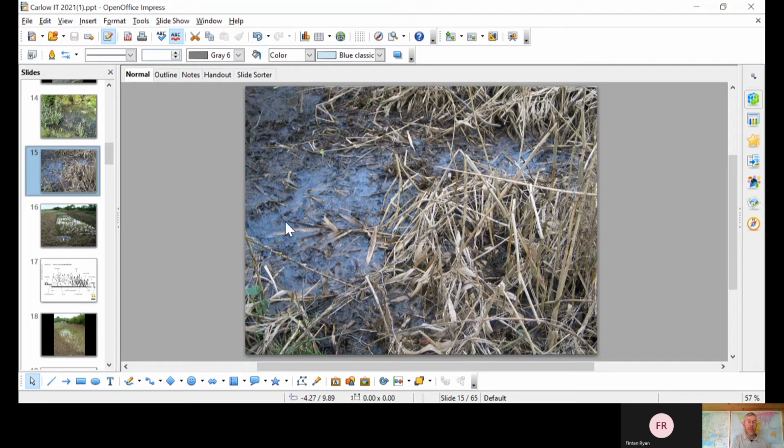So what we're doing really with constructed wetlands and reed beds is building a large creche for bacteria, essentially. So we want those bacteria that party so hard on their BOD loading, we want them to really proliferate within the wetland so that by the time the liquid gets to the far end, the bacteria have done their work, and then the water can go back into the receiving environment safely.